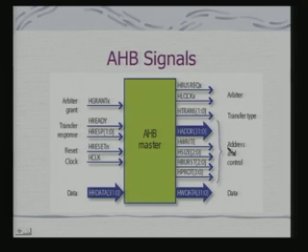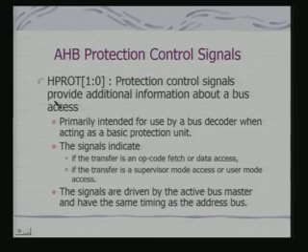and these are obviously the address and the control signals. This is the data, okay. You have got your write data bus as well as read data bus, which are two distinct buses, okay, and these indicate the transfer type. You have seen that there were signals called HPROT. In fact, this is a point we have not discussed earlier.